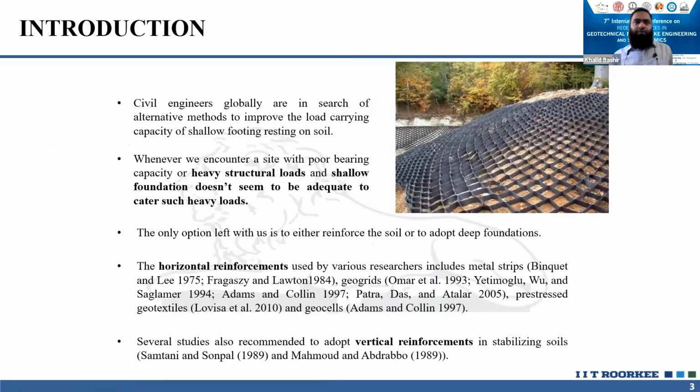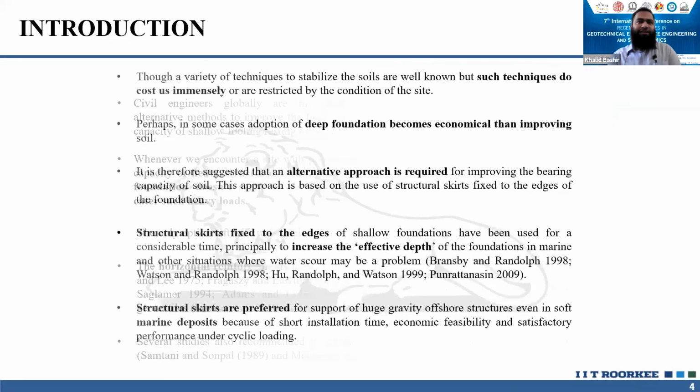Whenever we come to a site where there's poor bearing capacity, or we are having heavy structural loads coming from the top down to the substructure, we have two options left. Either we reinforce the soil, for which various researchers have come up with different techniques, such as horizontal reinforcement, geosynthetics, geomembranes, and many others to stabilize. Or we can go with deep foundations. But we usually see these techniques are costing us immensely. They are not that economical. And even in some cases, deep foundations become more economical than improving the soil. So it is suggested that we go for some alternate approach, so that we can improve the bearing capacity of our traditional